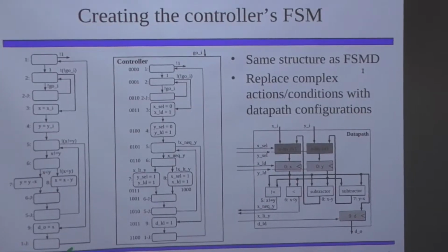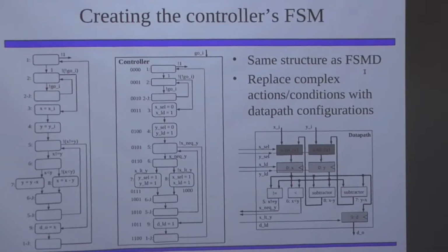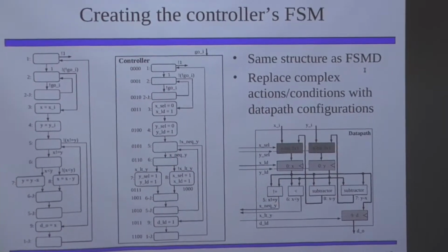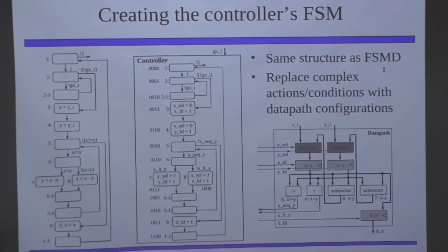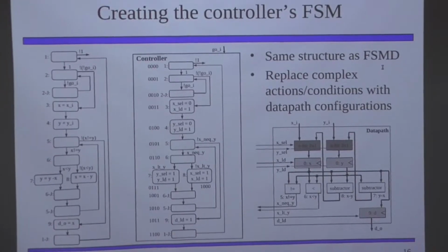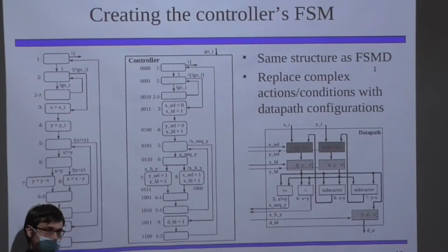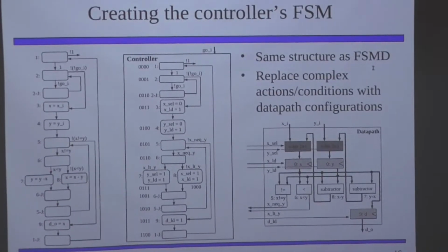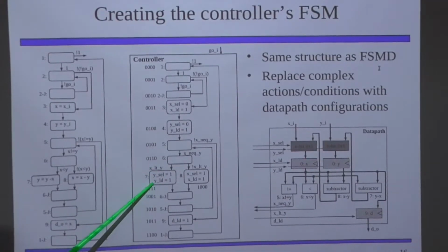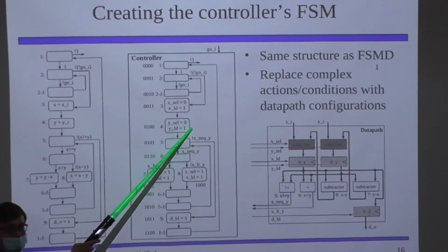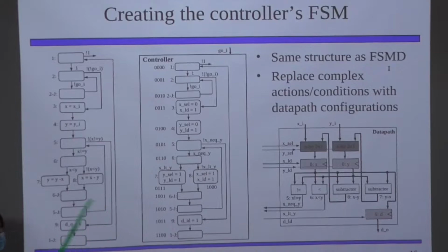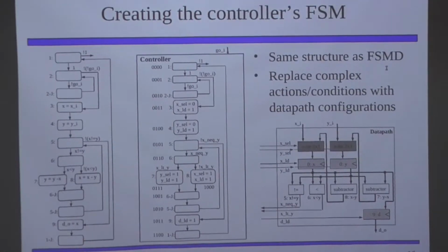So, in order to take this state diagram and derive from it a state diagram that would be useful in the controller itself, we have to extract those parts of the finite state diagram which perform data path operations, and we have to translate those into the corresponding signals that would need to be sent to our new custom data path module, right? In other words, we have to know when, inside of this controller state diagram, we need to load Y with something, what we need to select using the multiplexer, and at what time. Everything is tied to state, right? Very important idea.